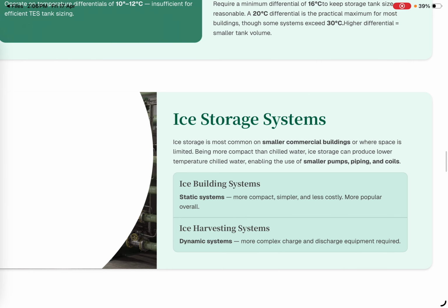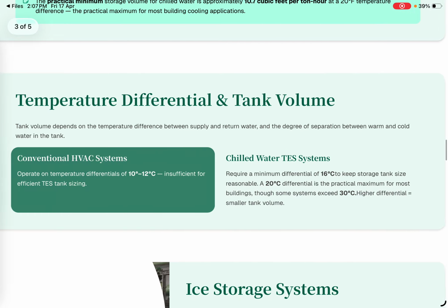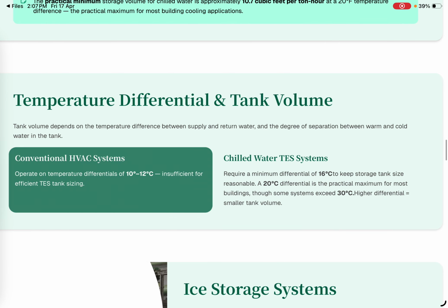We had one such unit in a central mall facility located in Nasik city of Maharashtra, where they built a thermal storage tank, a chill water storage tank, and operated the thermal energy storage system at night, making sure that the water was chilled and stored in the tank during the night. In the afternoon, when the AC requirement was there, they shut down the refrigeration system and simply operated the pumps and the air handling units and made sure that the mall was air conditioned